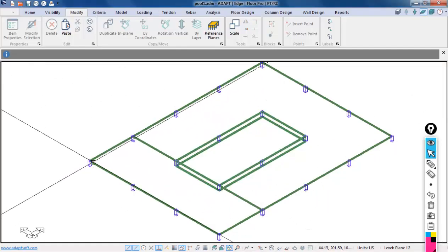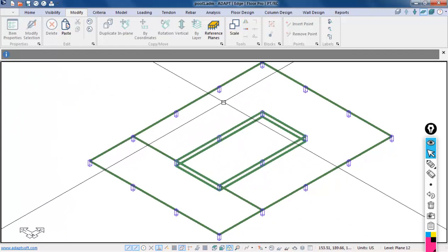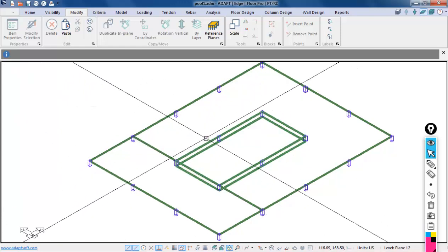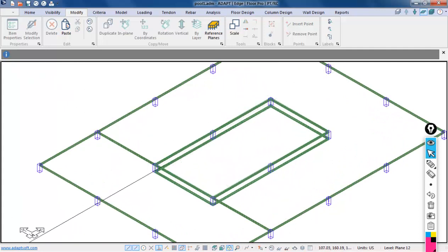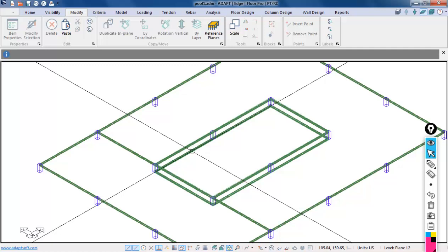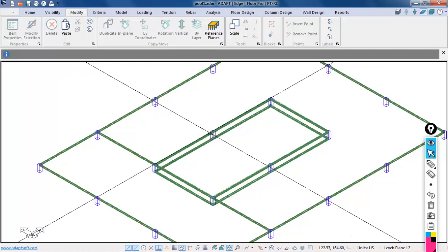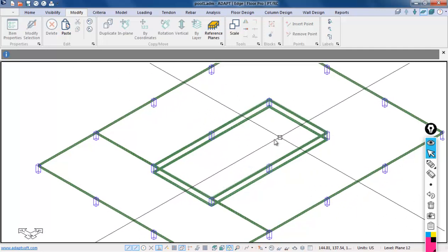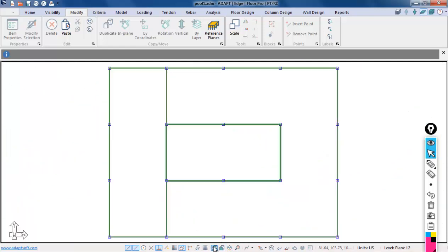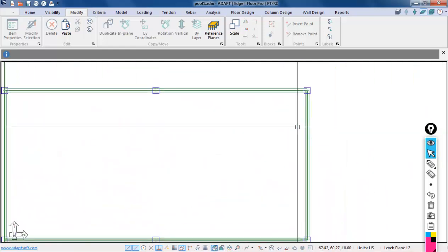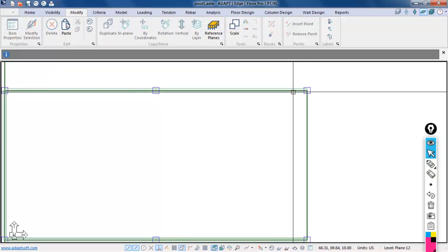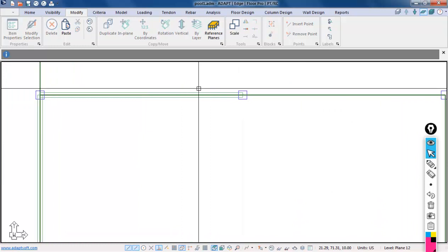So we've taken care of the column duplication by just deleting each of the columns one time to get rid of the stacking column. Now, because the physical node location of a beam frame element is below the midpoint of the column, which gets discretized also into two vertical elements like we talked about earlier, we need to replace these beams with walls in order to be able to analyze this properly, just due to the connectivity issues. So what I'll do is go ahead and get rid of the beams.